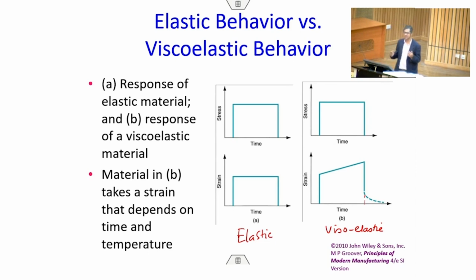That is because the material is so viscous, the molecules, once they stretch, take time to come back. So, although it is elastic behavior and the shape should come back to the original position, it takes time to come back. In the case of elastic materials, it happens instantaneously. It doesn't take time, but in the case of viscoelastic, it takes some time to come back. That is mainly because of this viscous behavior of the liquid. Although you have applied the load and the molecules have extended, they are stretched basically. So, coming back to the unstretched condition takes some time.